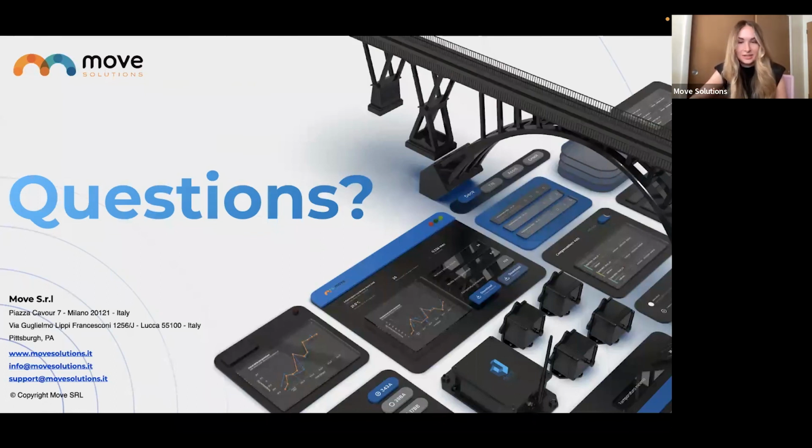So there's the trigger mode, which is if the threshold is surpassed. And with the cadence, if you are doing the synchronized acquisitions, you can do up to 1 per hour, but you can obviously drop that down too. So you don't have to do 1 per hour. Thomas, with the accelerometers at 640 Hertz, you'd be around the 2 years in the battery life.